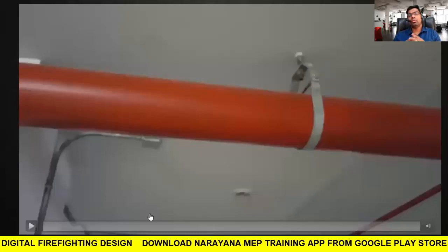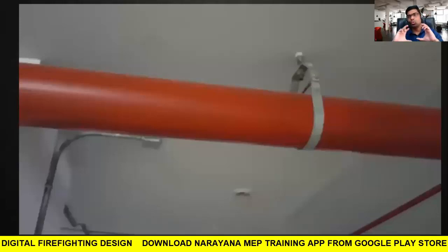Where more than one pipe is running, for example two 150 pipes, or 150 or 200 mm pipes running parallel, what do you have to give? You have to give C channel supports or L channel supports. And these are videos of the types of supports we have. In this video we have groove fittings.